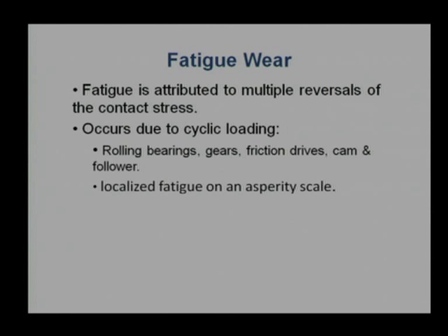That is why we are using the words multiple reversals, that is, the load is applied and removed. It is not a constant load. We can think about the asperities continuously: when the surface is sliding, the asperity comes under load, bends and regains its shape. So, loading and unloading is a continuous process.